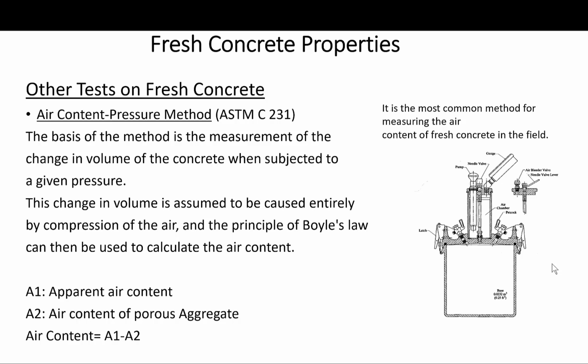And the apparatus is then reassembled. As you can see, it looks complicated, but it's not. The water is added through the petcocks, and the test pressure applied and adjusted using the air bleeding valve you can see here in the figure.